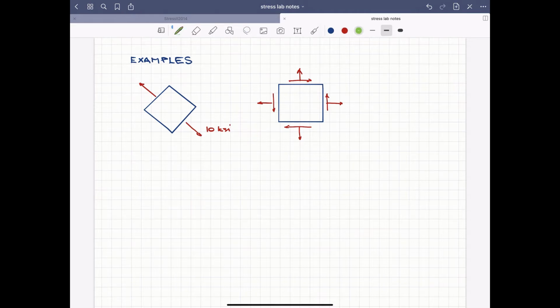Let's look at the 1D stress state shown on the left side, where that stress state is rotated as shown here. We want a stress block oriented traditionally with horizontal and vertical orientation. So I described the original state with a coordinate system x and y, here shown in green, and I need a coordinate system for my target system.